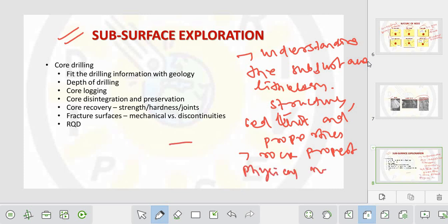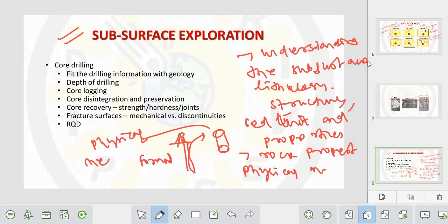जैसे मान लो ड्रिलिंग हो रहा है ना, तो ड्रिलिंग हो रहा है रिग पे, ठीक है. So if drilling is happening, we have to take the cylindrical core sample out of the different type of formation. ठीक है, हम cylindrical core sample collect करते हैं. Then we have to measure the physical and mechanical properties, okay, and the strength. All mechanical, मतलब बताया था ना, all those type of deformational properties like strength, hardness. Okay, so these are the important deformation properties we generally measure in the lab.